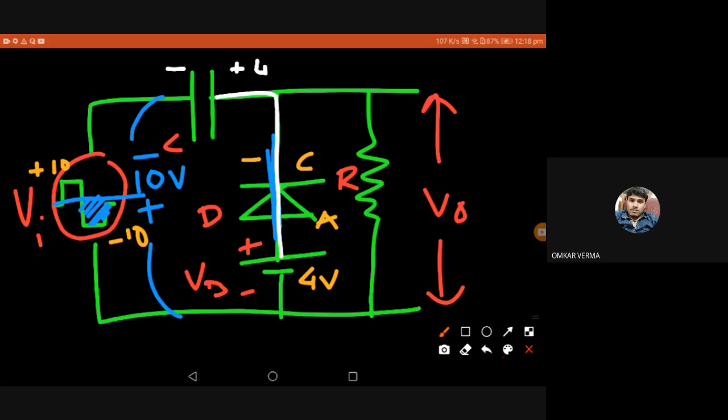The input is giving negative charge on one plate. So what is the net effect? What is the potential difference across the terminals of the capacitor? That is simple, it is 14 volt. That means both the input and VB act as series battery supplies, you can see the sign minus plus, again minus plus. Both are going to add.